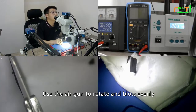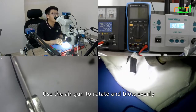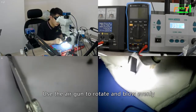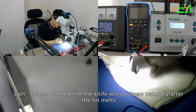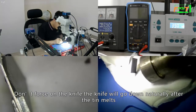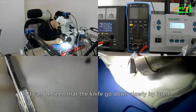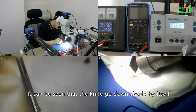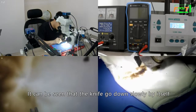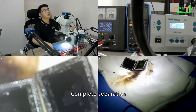Use the air gun to rotate and blow evenly. Don't force the knife. The knife will go down naturally after the tin melts. It can be seen that the knife goes down slowly by itself. Complete separation.